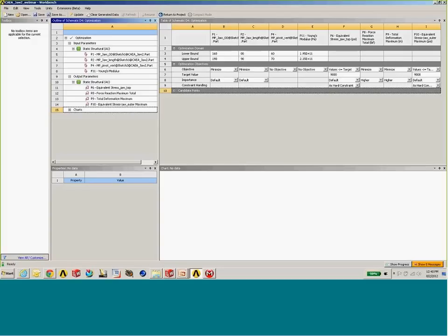Moving over to our input quantities on the left here, the Young's modulus I really have no control over, so I leave that as no objective. The same with the vertical pivot. I found that had a relatively weak correlation, so we're not going to assign an objective to that quantity. But in the case of the jaw OD and the jaw length, I'd like to make the vice grip as small as possible, because that minimizes the amount of material required and the weight of the tool. So I'm going to try to minimize those as a goal.